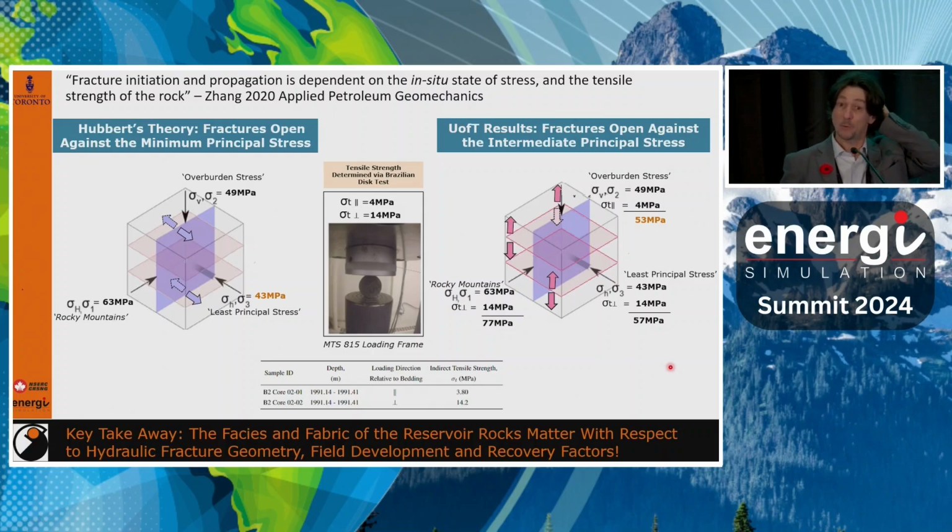And when you account for that in the failure mechanism, you add that, for example, to the stress state, all of a sudden the minimum stress value that you need to overcome was exactly the one where failure was happening. It was basically against sigma 2, because of the particular stress state that we had. So we think that we could explain and incorporate this in the model.